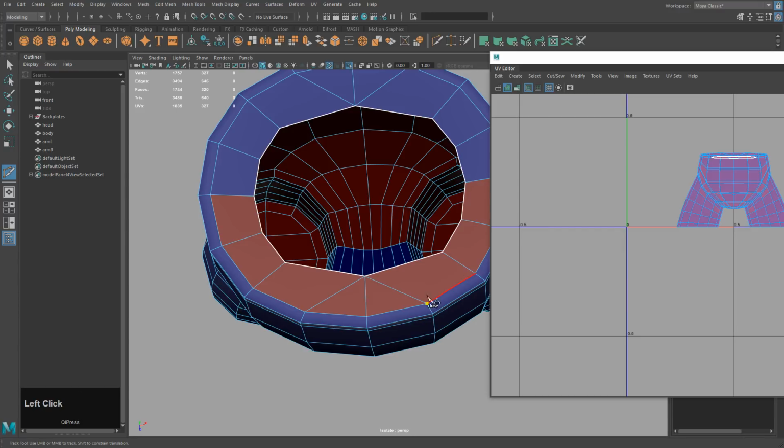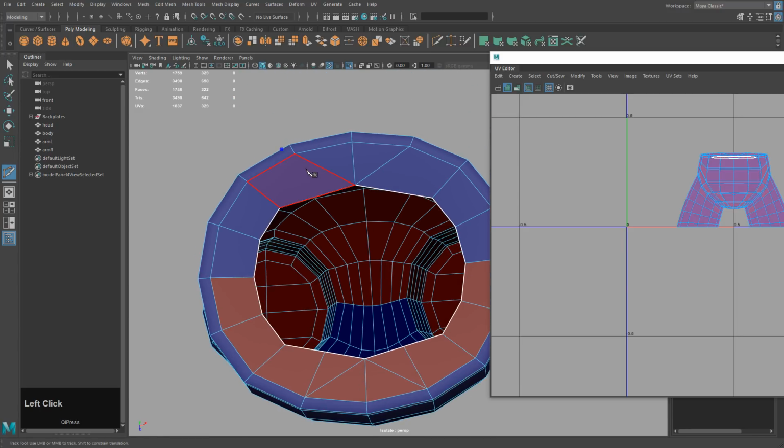So I'm going to use the multi-cut tool, drag a selection, click it again, drag a selection, drag on this edge, and then if I hold shift and drag, I can put a 50% there. Hold shift and then drag on that edge, and the same on this side. Oops. Hit delete when you mess up, like that, like that. Delete these extra edges.